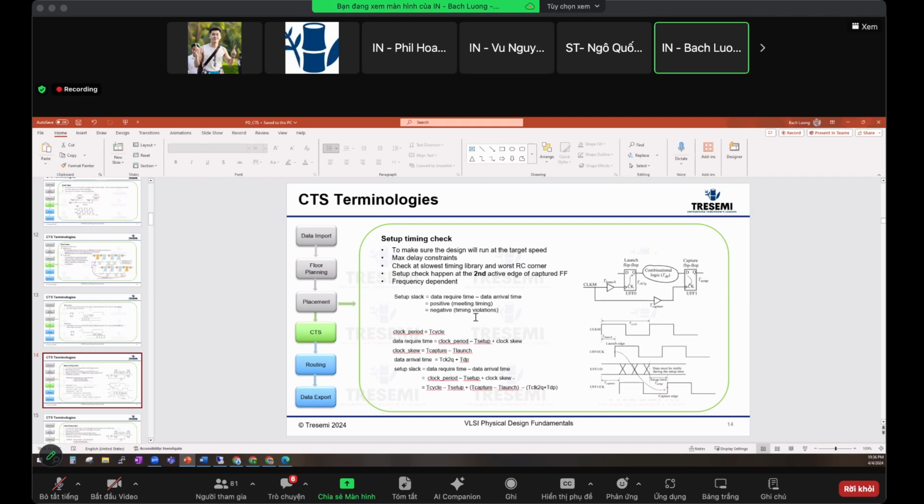But then the silicon comes back on a good lot, and it can run at 2.4, so we take that and say we run at 2.4. We're always going to market the fastest one. But some of the CPUs on your phone may run at 2.2 or something like that. It depends. The silicon could be a lot faster, and some could be slower too. It's on the bell curve distribution.